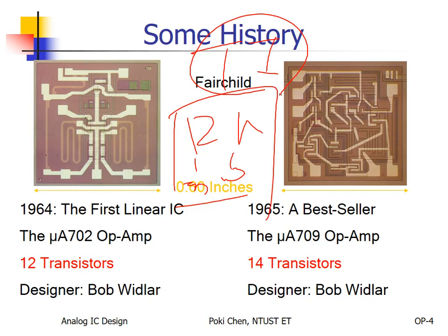Anyway, even though they don't show the detailed content, they still decap the chips of others. They decap layer by layer and take micro photos. And right now, I think they apply some AI to automatically recognize the equivalent circuit. After they get the exact circuit, they duplicate it with some modification.